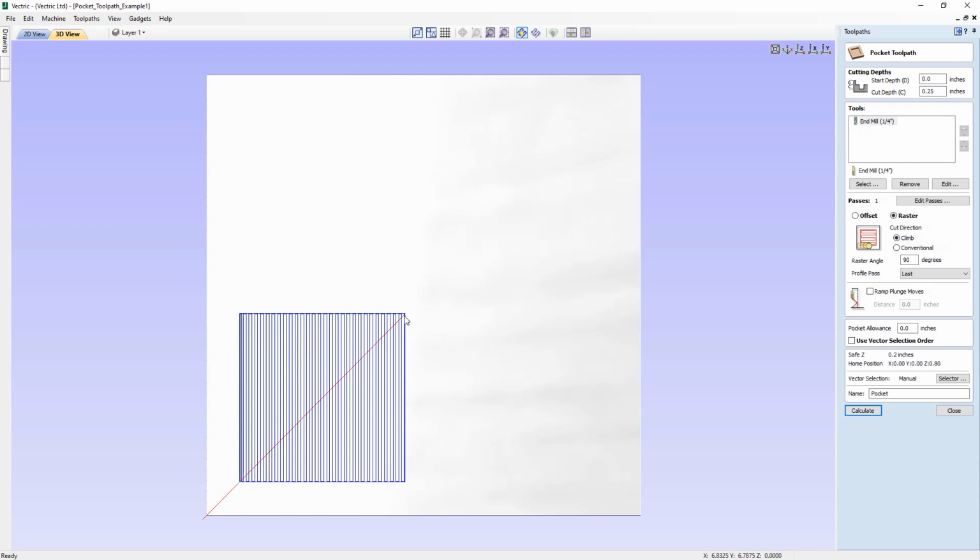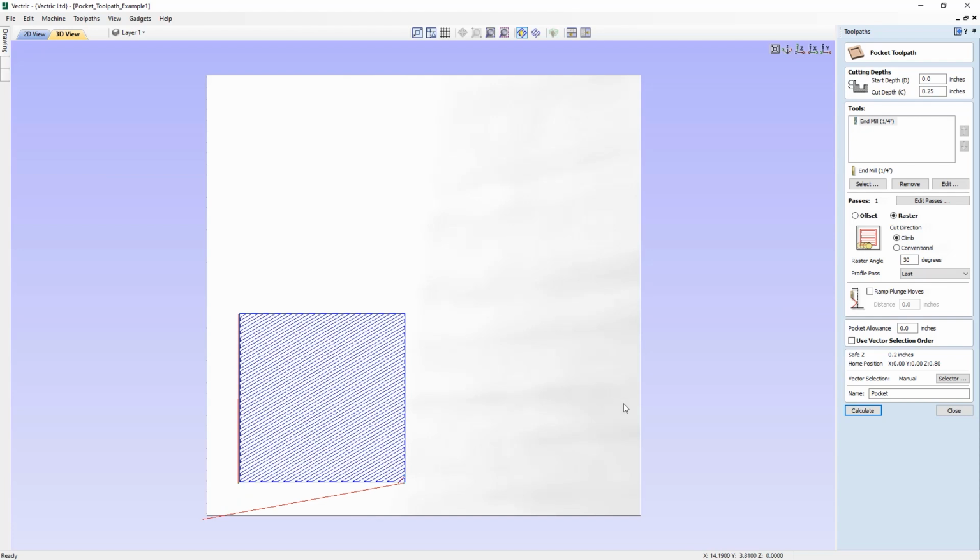And you can see we'll start here, it's going to come down and go back on itself, up and down, like the pattern that you can see here. Let's say, for instance, you wanted to do a 30-degree angle. We could simply put in 30 degrees in there and then press Control and calculate, and we can see that that is 30 degrees from the x-axis, and you can see the result of that there. Okay, so let's just set the angle back to 0 here.